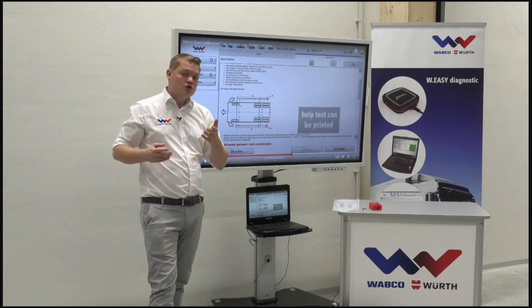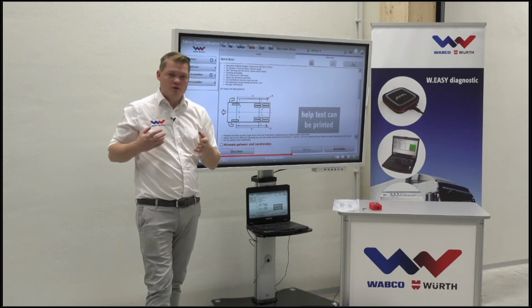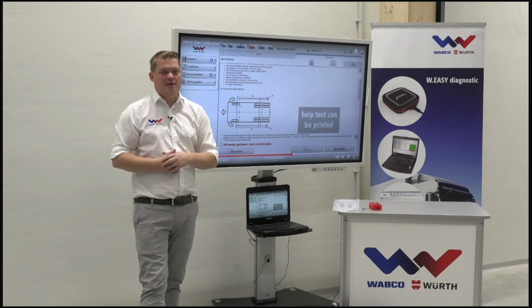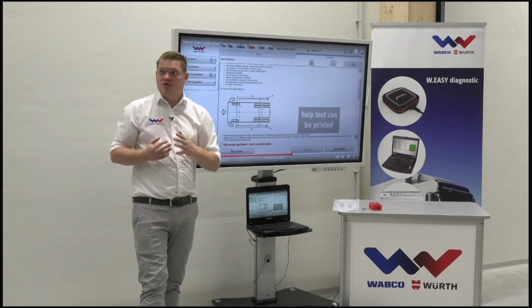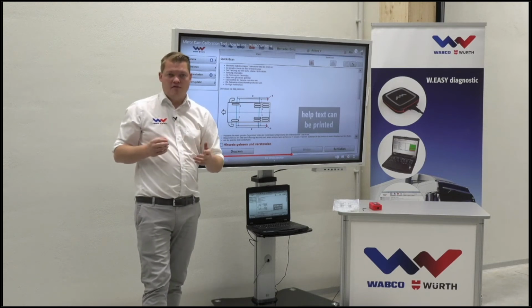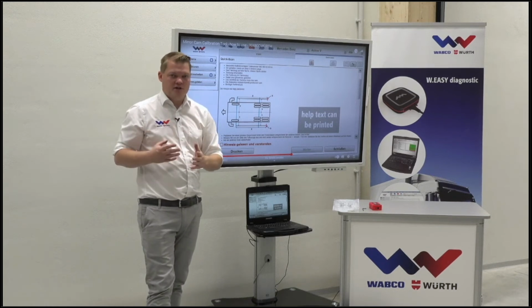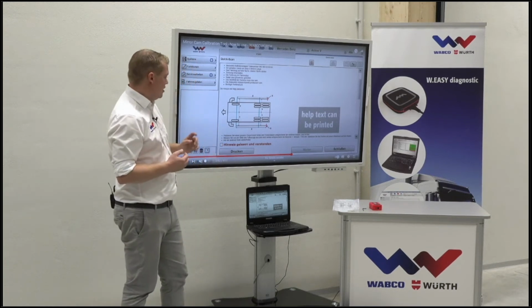If you're able to keep the cameras on during the windscreen exchange, fine, no need to calibrate the cameras. So important to know is only when you take them off, when you have a repair and exchange of the system, please calibrate the system on both sides. Important to see.